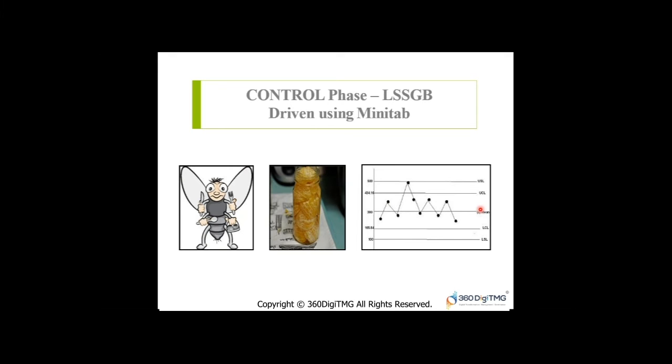Just to give you a brief about this, let me explain this control chart which is present here. Upper specification limit and lower specification limit are provided by the customer, end user. And these specification limits will not change. They would remain the same. And your control limits, upper control limit and lower control limit, are calculated based on the data points which get generated. And these black dots are your data points, right? And here we have the mean.